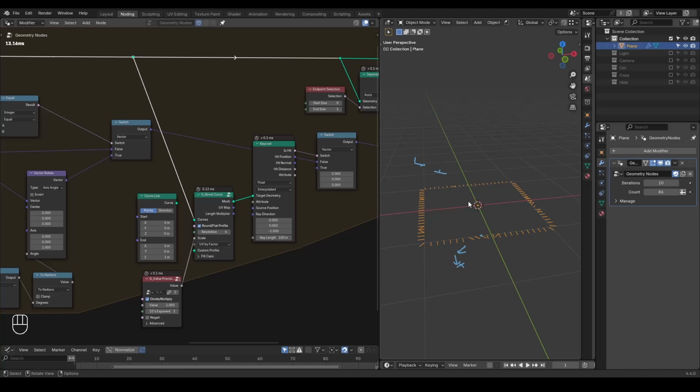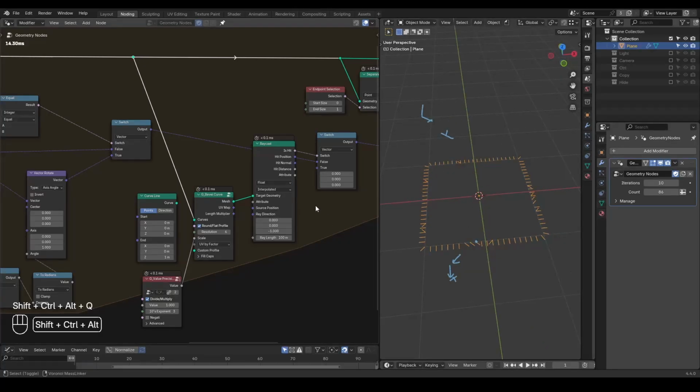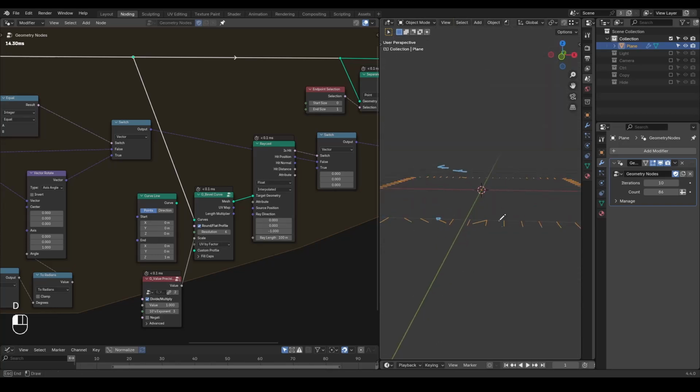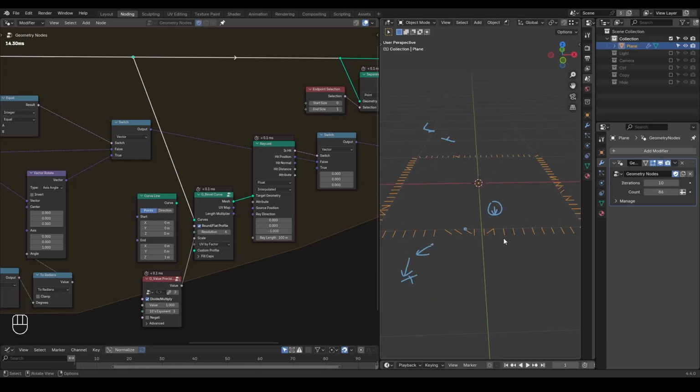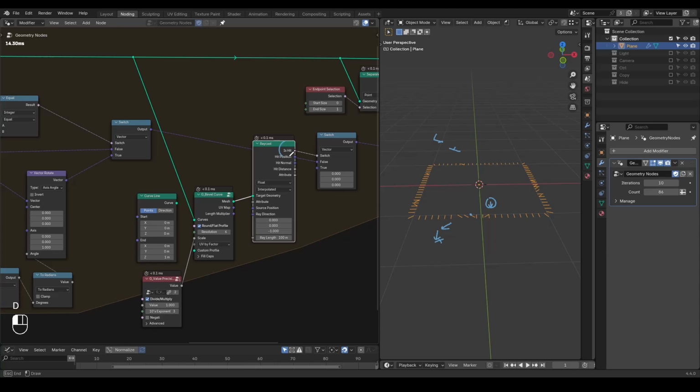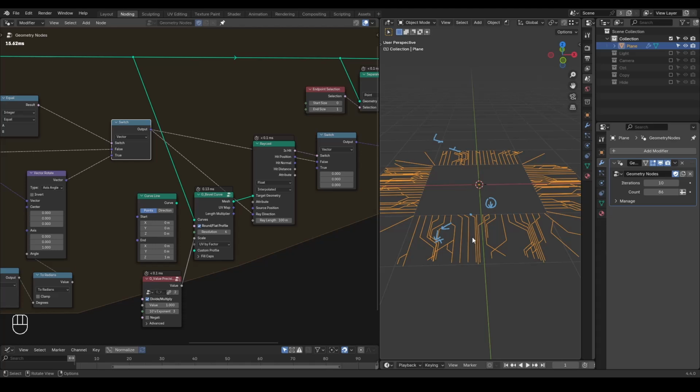And immediately you will have an issue with the viewport. This is because right now we're shooting a ray downwards at the 0, 0, -1 direction. So imagine that you're forming a tube-like structure and you have a point to sample the collision. A ray downwards means that it will hit itself. That's why all these tube points are giving a collision result to stop moving. In this case, we're going to replace the direction with our forward direction.